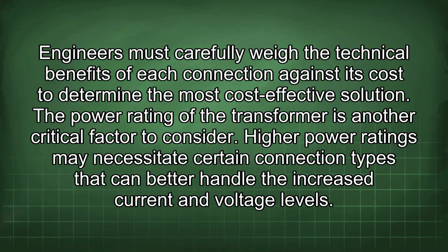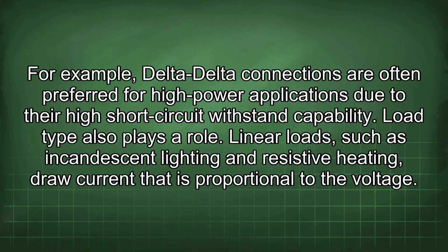Higher power ratings may necessitate certain connection types that can better handle the increased current and voltage levels. For example, delta-delta connections are often preferred for high-power applications due to their high short-circuit withstand capability. Load type also plays a role.